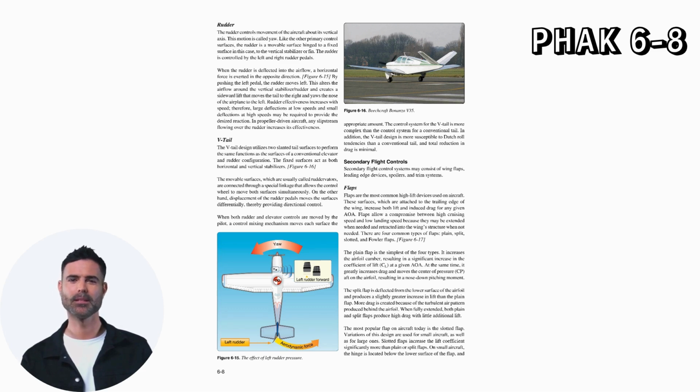The split flap is deflected from the lower surface of the airfoil and produces a slightly greater increase in lift than the plain flap. More drag is created because of the turbulent air pattern produced behind the airfoil. When fully extended, both plain and split flaps produce high drag with little additional lift. The most popular flap on aircraft today is the slotted flap. Variations of this design are used for small aircraft as well as for large ones.